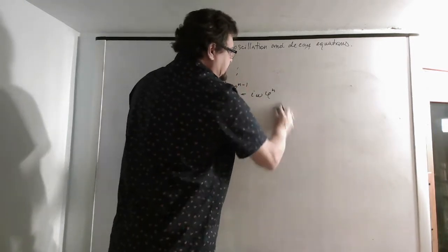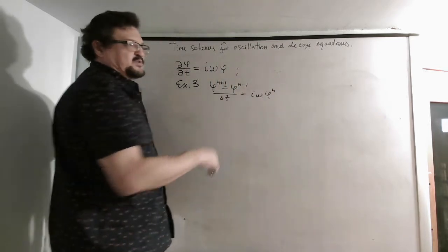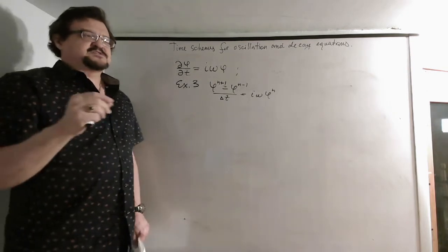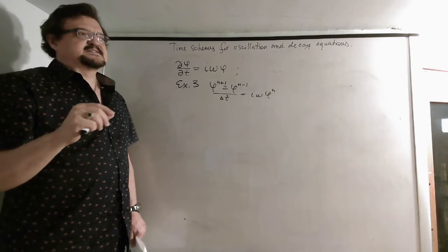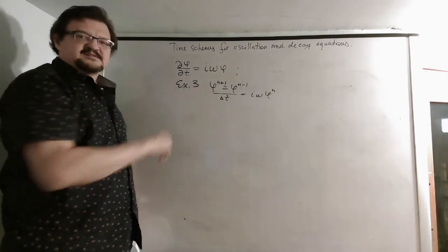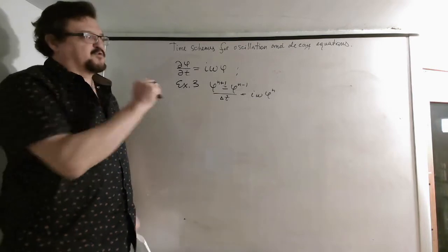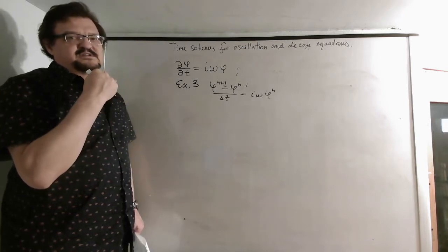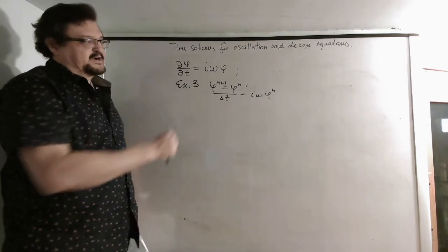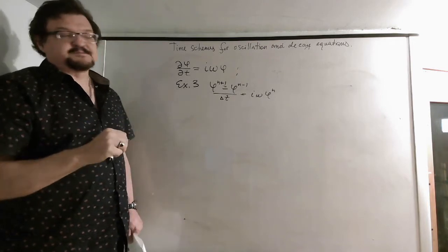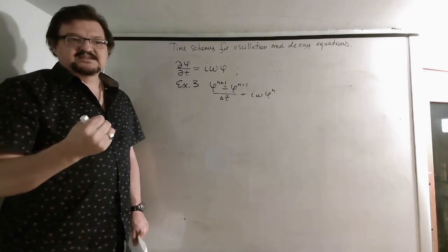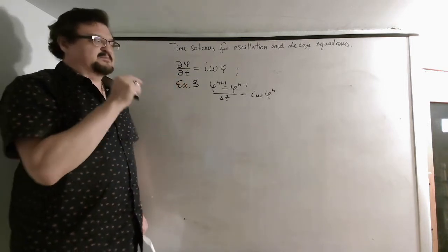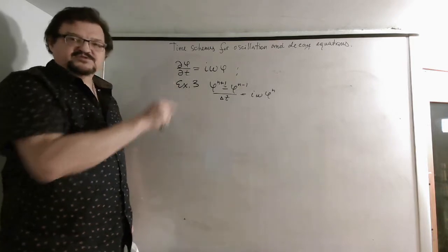But because it's a linear scheme, the stability of this scheme will be combined with the stability of the other terms. That's actually an important point when you consider linear stability due to advection, diffusion, and in this case oscillation. Your delta t should be the smallest of all three criteria that you would get, separate for advection, separate for diffusion, and separate for, say, oscillation, in this case, or Coriolis force. The time step will be dictated by the smallest allowed time step for each of those processes.